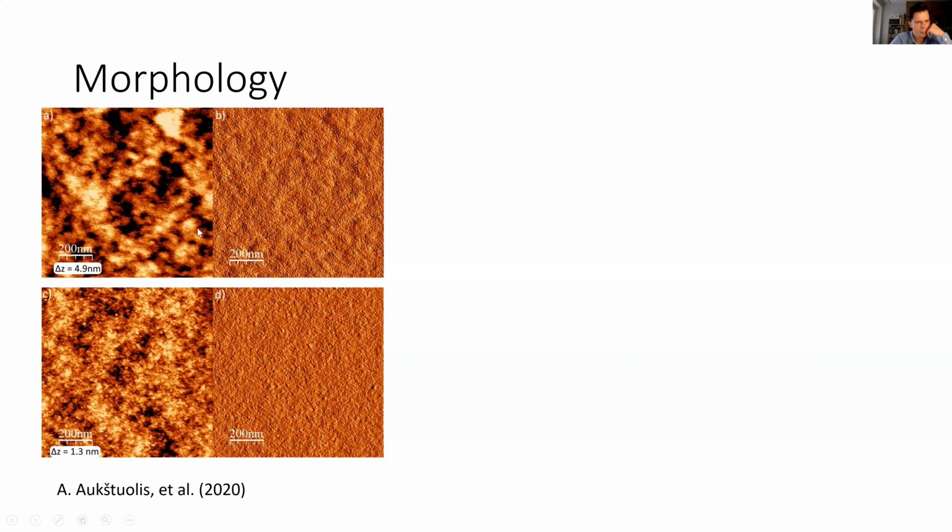So this was interesting, and since we did measurements at higher temperatures, we thought we should see how the differential scanning calorimetry of the material looks, and it showed that around 112 degrees Celsius there is the glass transition temperature of this material.